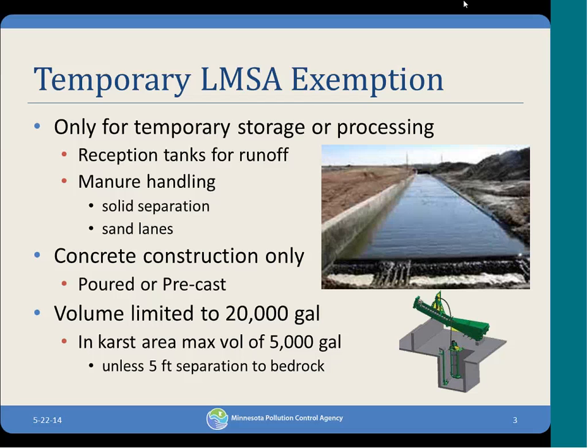Sure. Because it's 28 days for a full cure on it? Concrete usually, right around there. That's why they're not wanting to have backfilling before the slats are set. Right. Complete backfill, for stability and making sure that the cure happens with proper support. Yep.